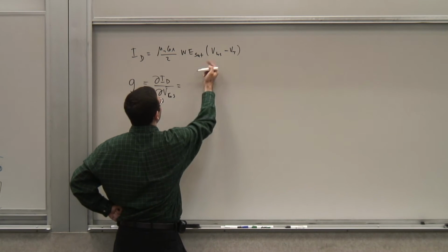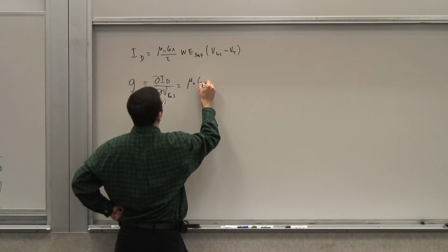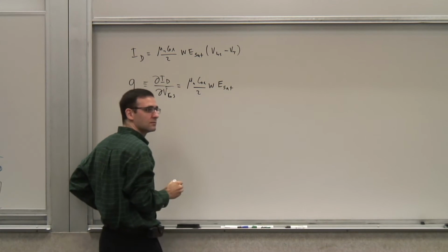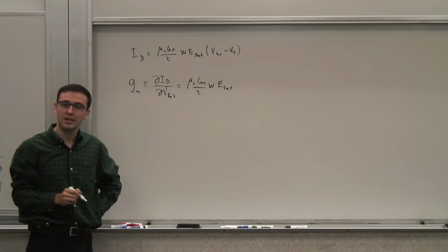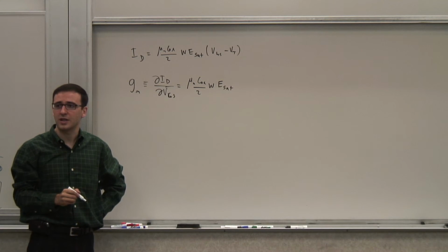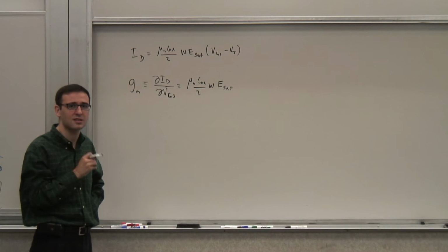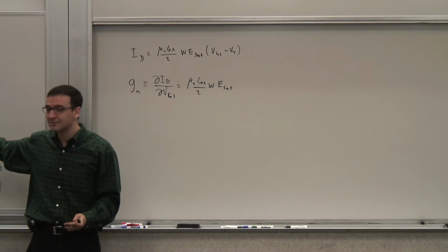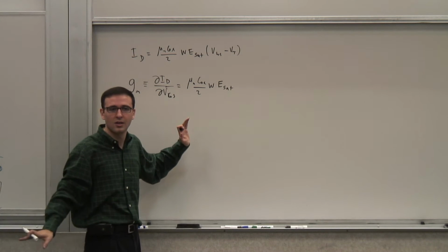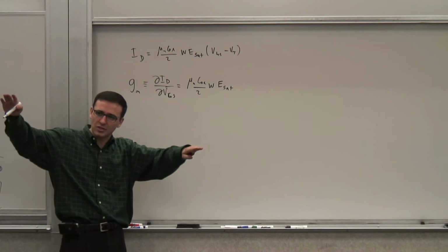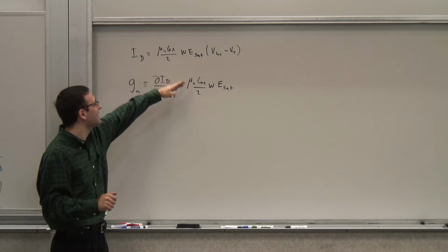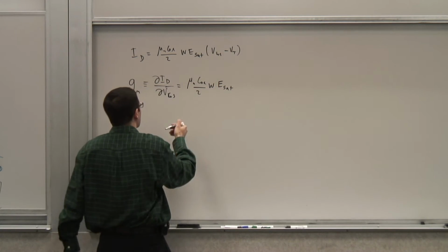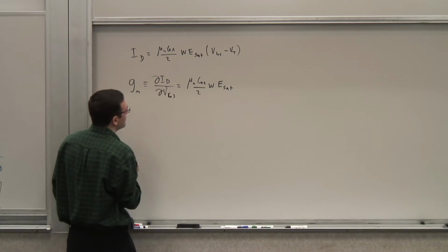So let's see how it behaves now. This is a linear dependence, so the transconductance basically becomes independent of VGS in the first order. So now my gate overdrive does not buy me anything in terms of transconductance if the device is deeply velocity saturated. In reality, the transistors are somewhere between these two modes, so by understanding the two extreme cases, we understand where we are. The dependence is going to be somewhat linear for most of the transistors that you're using. Of course, it depends on the voltage. So that's my gm.